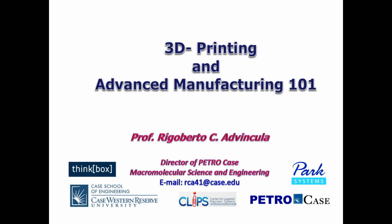Of course, this can be complemented with lithography. Photolithography and electron beam lithography are methods by which patterns or objects can be created, but this involves removal of a material or use of electron beams or electrons to do chemical conversion. So the answer is, in the nanometer level, yes, it's very much in that direction. At the atomic level, perhaps again with the use of high vacuum STM, it's possible to move atoms, it's possible to stack atoms, and it's possible to 3D print atoms.